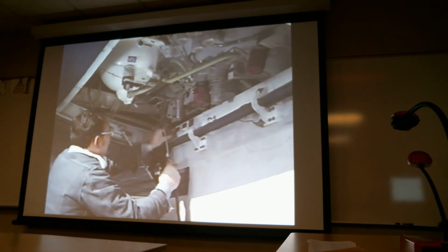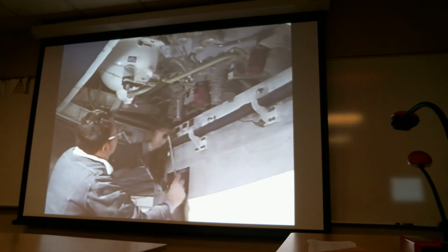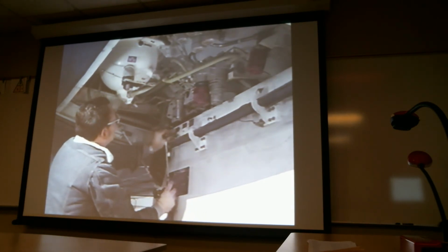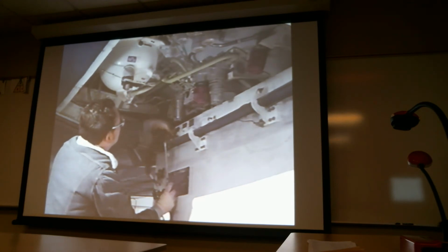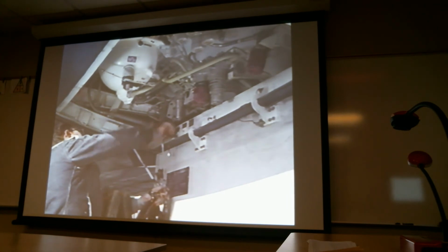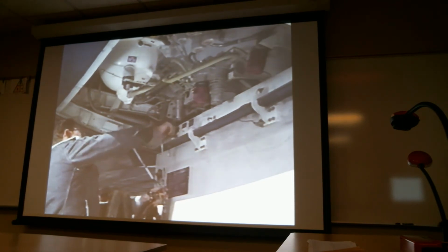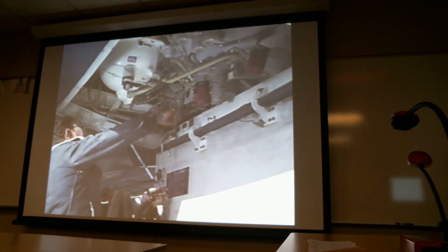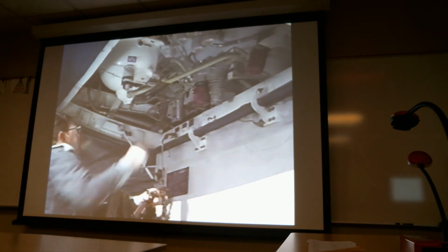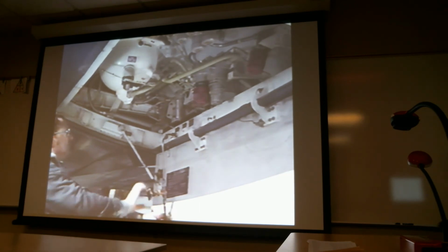Attach the pressure fill hose to the fitting. And service the system while monitoring the fluid level on the remote quantity gauge.